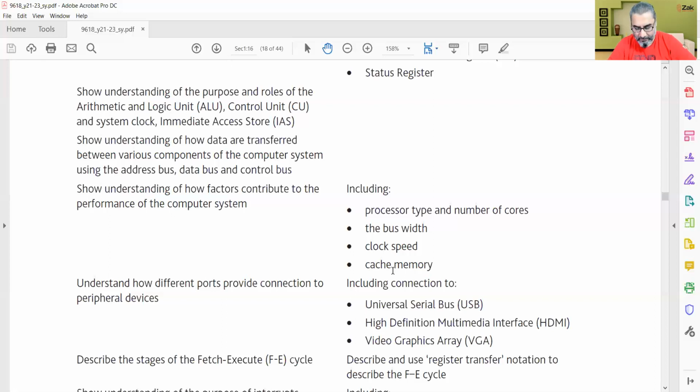Before that, it was just waiting for every other instruction to be at its disposal. So the use of cache memory can improve processor performance. It is similar to RAM in that its contents are lost when the power is turned off. Cache uses static RAM, SRAM, which we will discuss later, whereas most computers use DRAM for the main memory. So the main memory RAM is DRAM, which is dynamic RAM made up of capacitors, and inside the microprocessor, the memory is SRAM, which is static RAM.